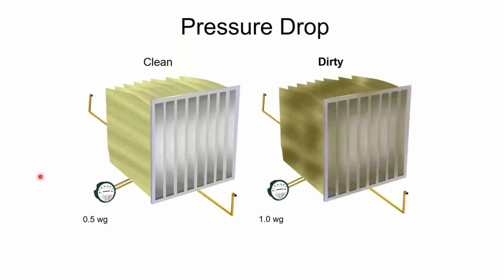All right, one of the other selection criteria for your filter is specifically when you should change it. You should be changing filters based on pressure drop, especially if you have expensive filters. The more expensive your filter gets, the less often you want to change it, right? The filter I use is pretty expensive, I want to say it's like $80. But I can usually get away with changing it almost on an annual basis. I change mine based on pressure drop at home because I'm a dork and I do things like that. At a house, you don't normally do that, but I do.